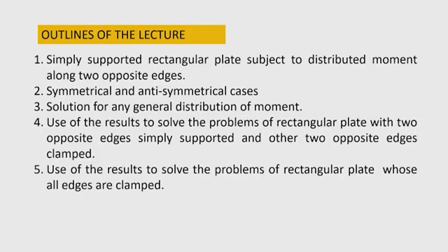Today's outline of the lecture is: first, a simply supported rectangular plate subjected to distributed moment along two opposite edges. Then we shall consider symmetrical and anti-symmetrical cases for the moments. Then number 3, solution for any general distribution of moment.